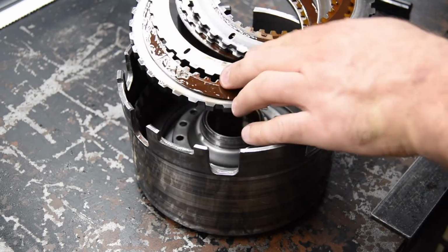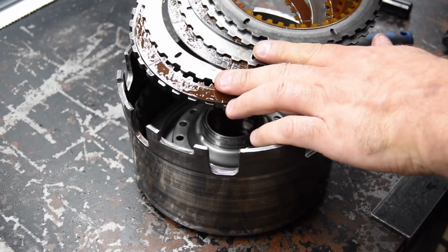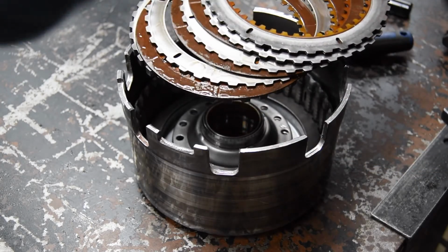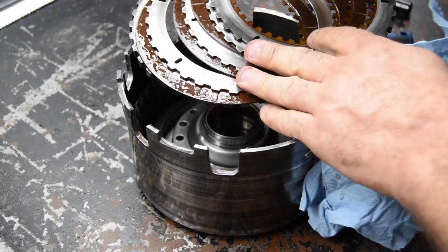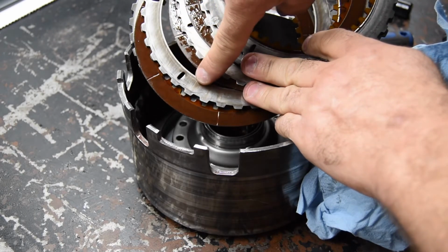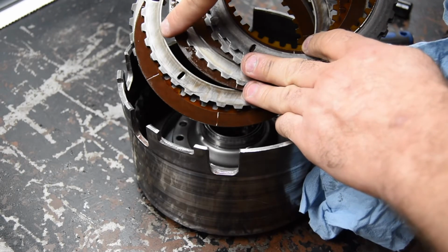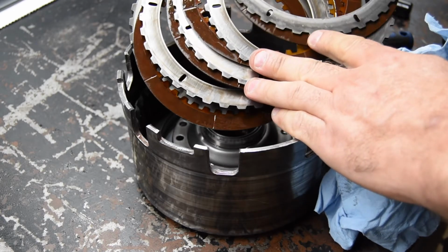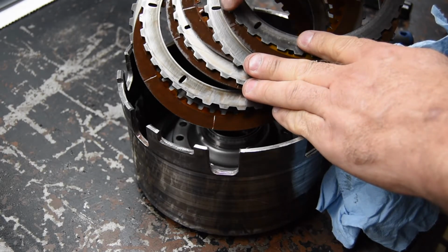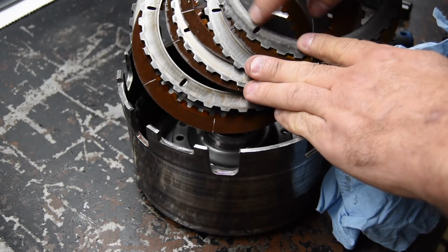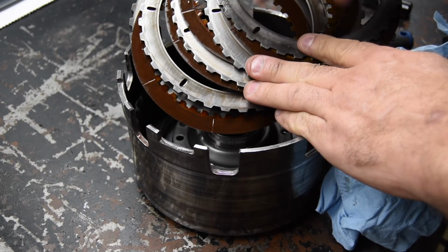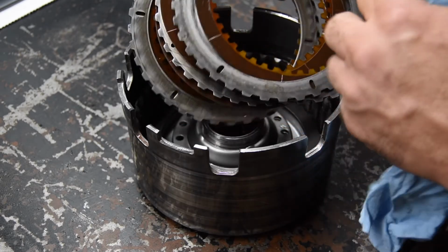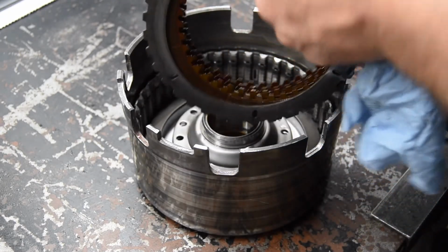And we can see that we've had some heating in them, which is perfectly normal with this transmission. But we've got right through here, you see that little dark spot there. That dark spot indicates it's just had a little bit of heat, but nothing serious. So this clutch is actually in good shape. We've got these little holes there to help evacuate the fluid that gets stuck in between them, just to make the shift a little bit more reliable and consistent.